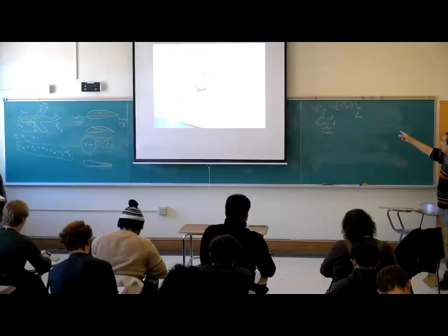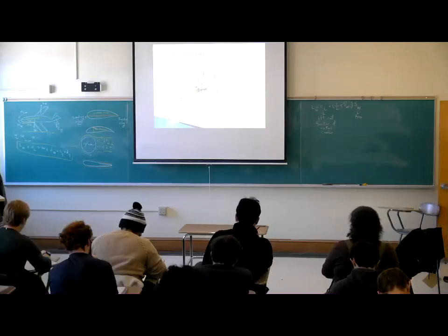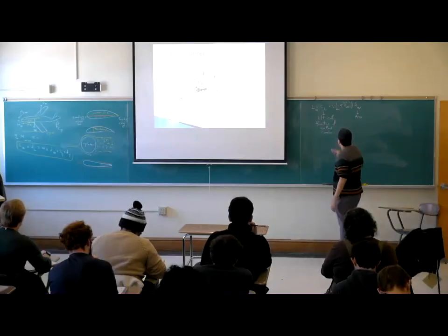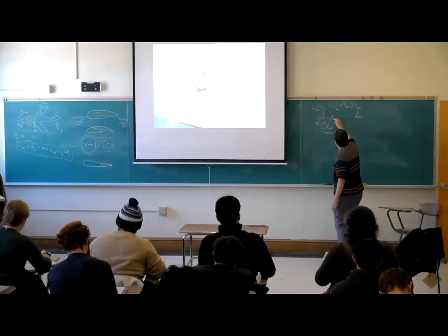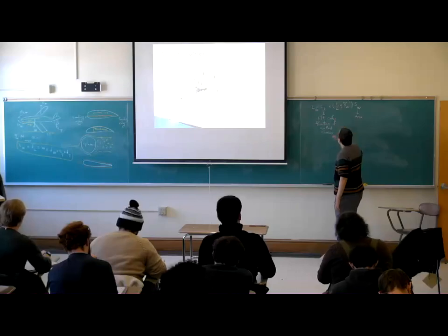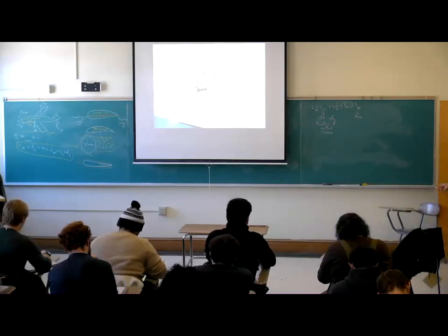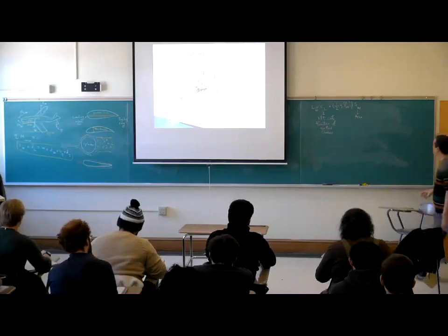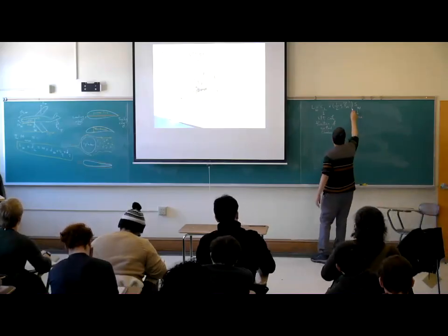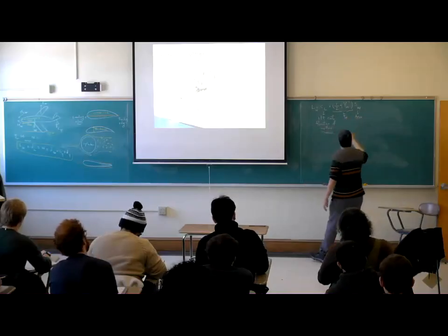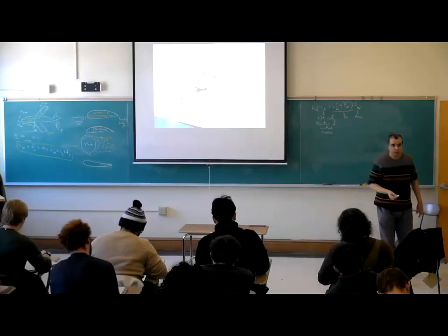So the lift of the wing is a function of the lift coefficient, which is a function of airfoil camber, multiplied by dynamic pressure, Q infinity, multiplied by area.